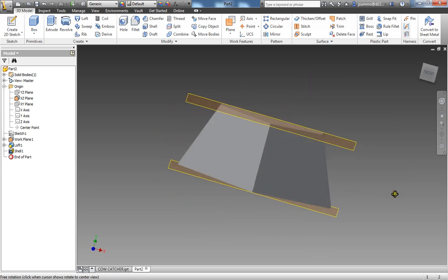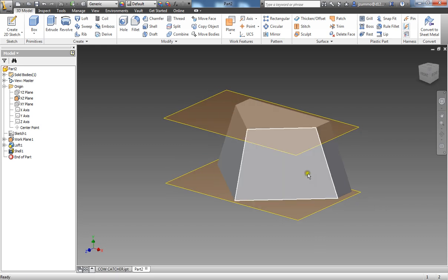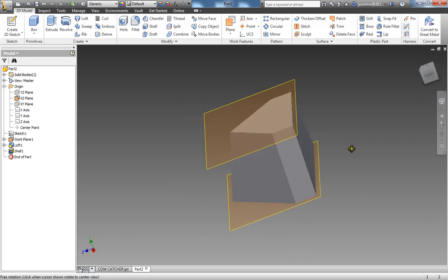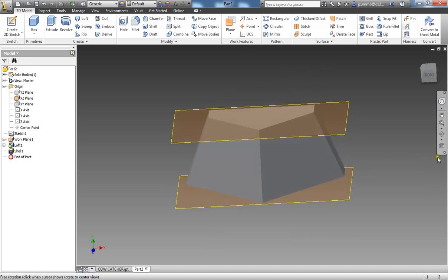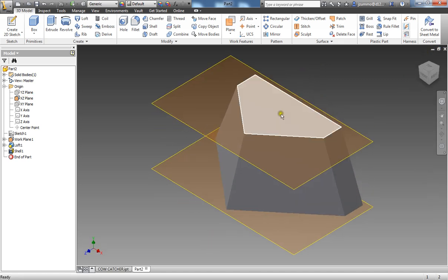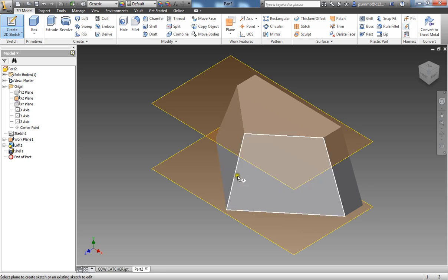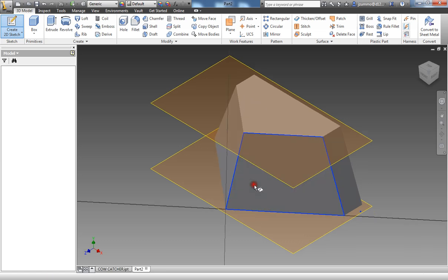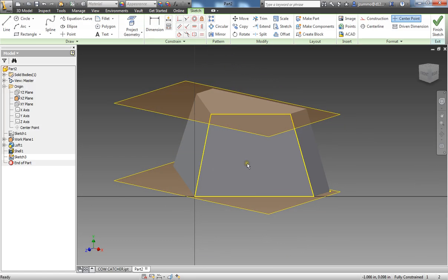The last 2 things I need to do here are going to be putting those indentations on the front of both of these sides, and those 3 little pegs on the back with the chamfers. So doing the front parts here, the little indents, actually not too bad. We're just going to go ahead and say create a sketch, and you can do either one of these sides first. I'm going to pick the right side here. Notice that these lines here are yellow. It actually projected the geometry for us for that profile that we see here.